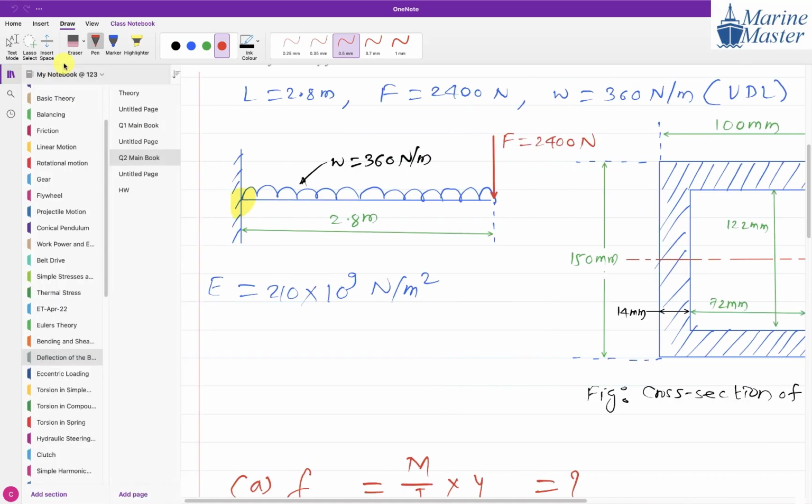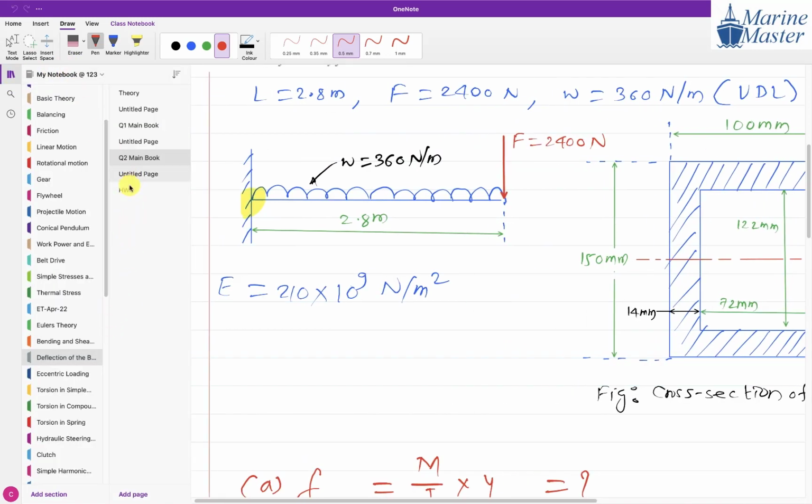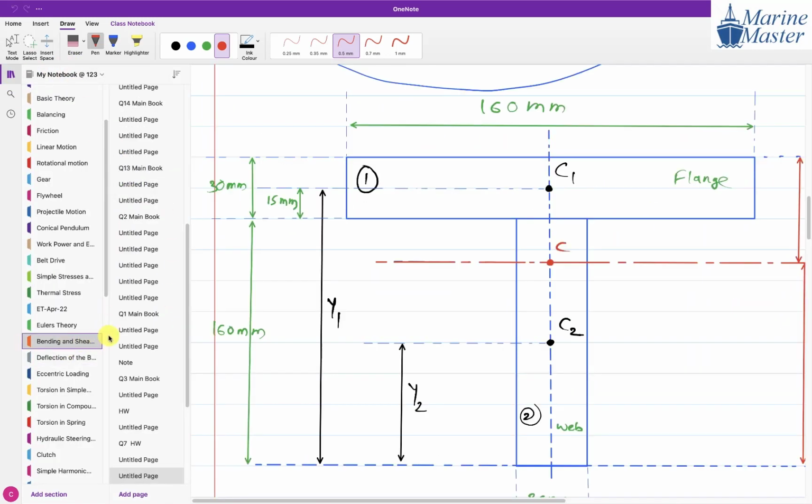See, one question that I am going to send you a solution today from chapter 5. Whenever we have a cantilever scenario, always don't worry about the hogging and sagging. Just try to take the effect about the fixed edge. If you are considering one direction, try to consider clockwise positive, anti-clockwise negative. Always try to keep this in your mind whenever we have a cantilever scenario for the calculation of bending moment. Here we are calculating bending moment.